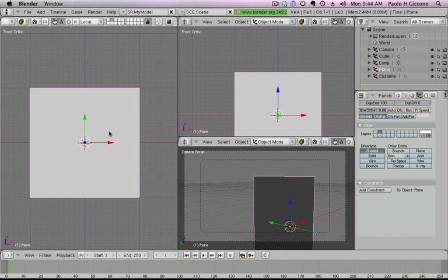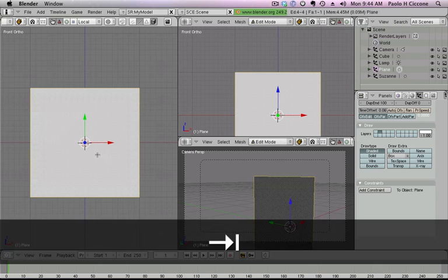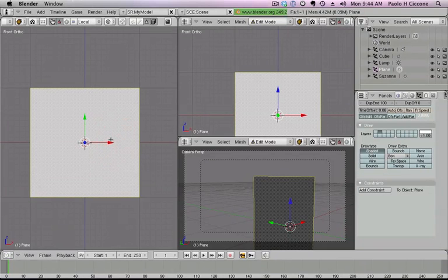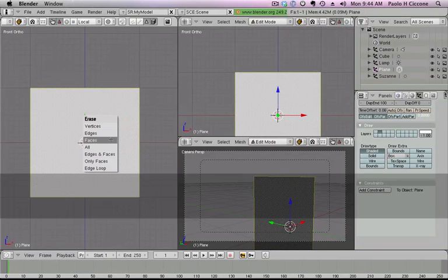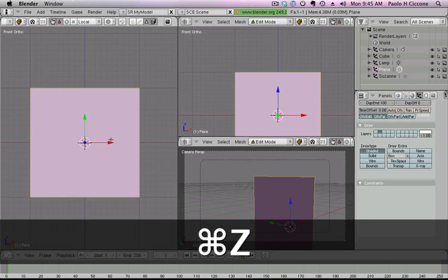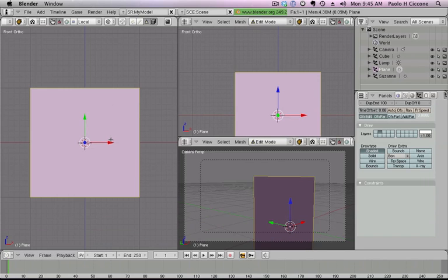carved in it. Now I cannot simply say, go to edit mode and select the face mode and click on this face and say, hey, delete the faces, because the entire plane goes away. I mean, the plane is one face. If you remove the face, it's gone. What I like to do is to basically keep the frame, the so-called frame, and remove just the surface.